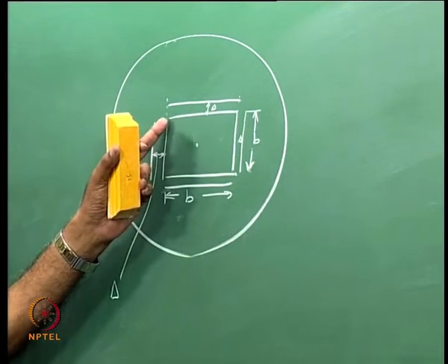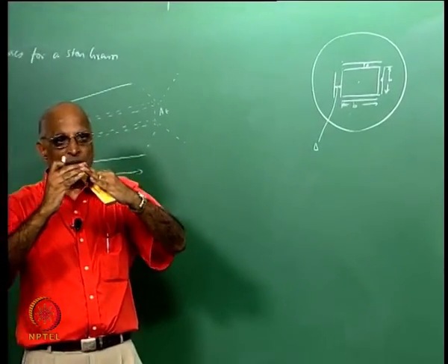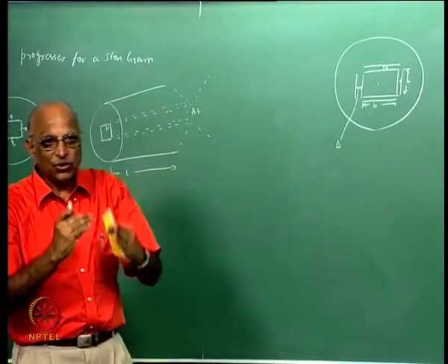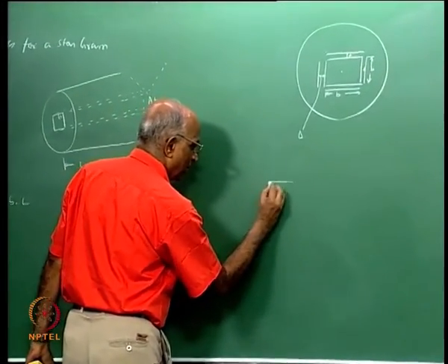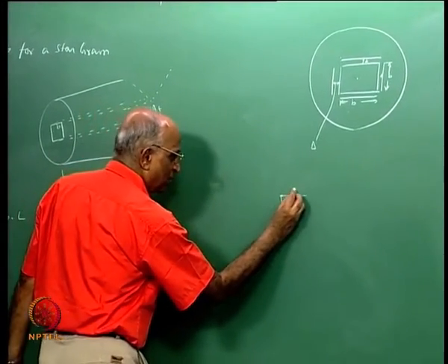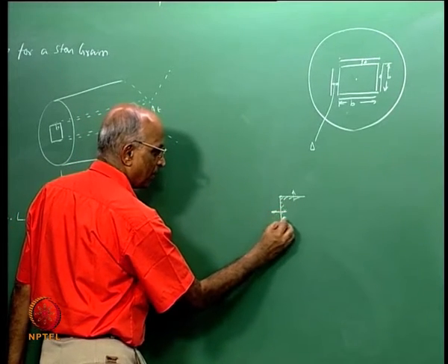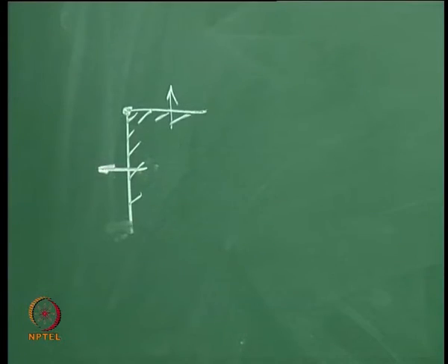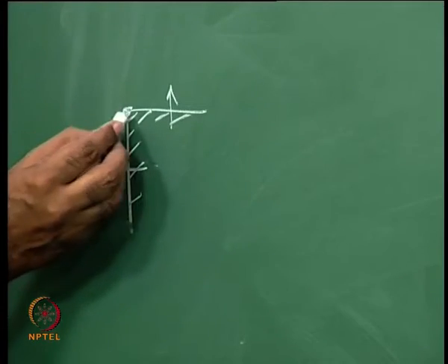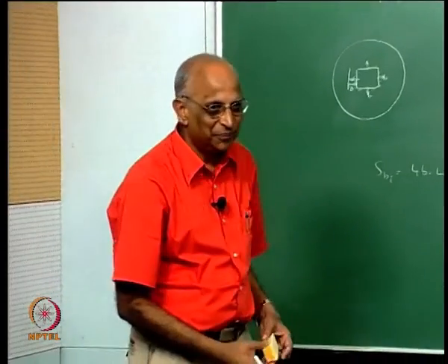How do the points evolve? How does the vertex of the two lines evolve? We said burning is always normal, therefore how should it evolve? Let us say I have this vertex here, burning surface is normal here, burning surface is normal here, this is the surface which burns. How will this point evolve? Normal? The point will evolve like what? How would you look at this problem? Maybe you all should give me an answer.